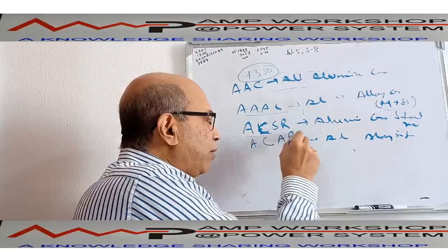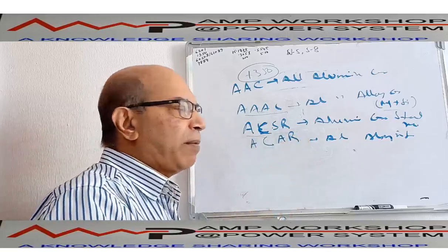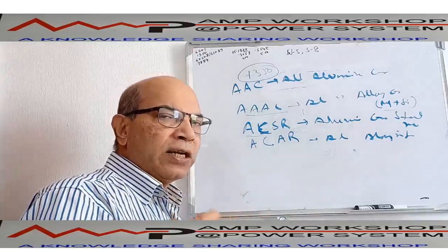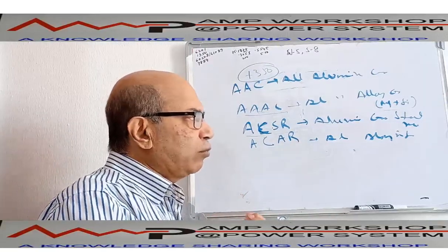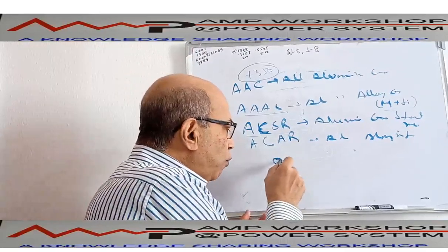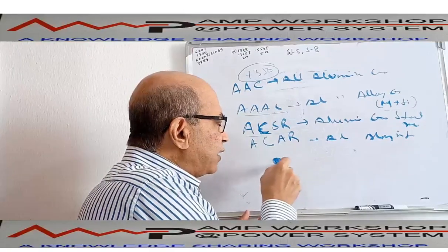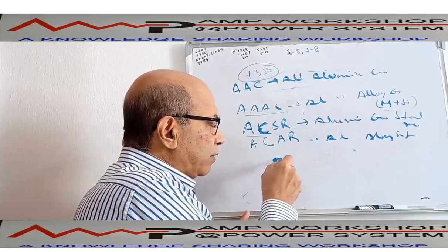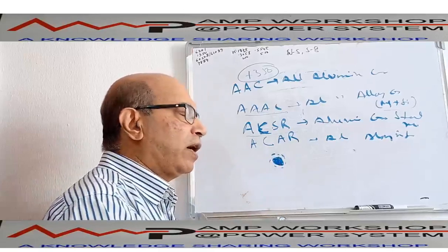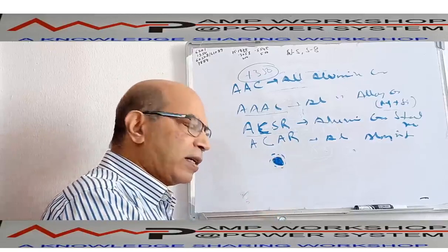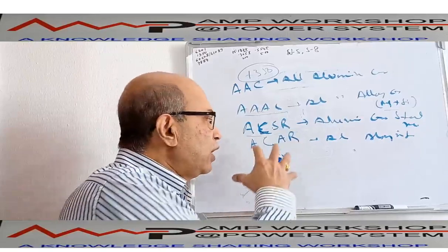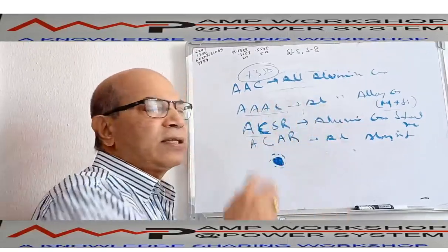And when you make an aluminum conductor steel reinforced, in this case, I have already told that aluminum has a poor mechanical strength. To increase the mechanical strength, what we do is put a galvanized steel conductor at the center, and along the center we put the aluminum conductor. This center galvanized steel has a high mechanical strength, so the conductor's mechanical strength automatically improves.